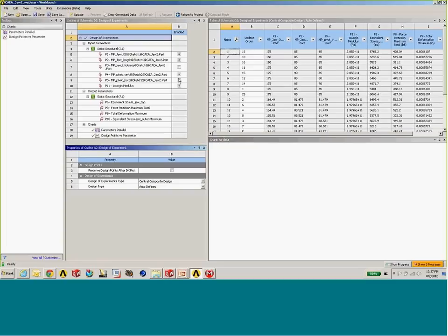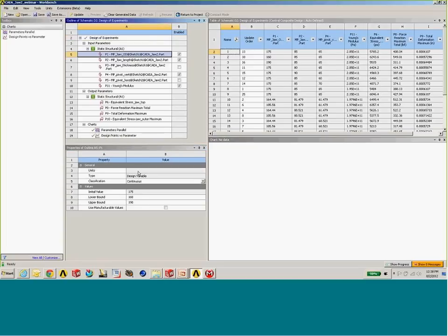Next, under our input quantities, we eliminate the input parameters that we saw had weak correlation, and then we specify the lower and upper bounds of our parameters, and the type of parameter each is going to be defined as. It could be continuous, so it's going to be an upper-lower bound within that range, or it could be a discrete parameter, where this particular parameter can only take discrete number values in that process. So it all depends on how that parameter affects the overall design.